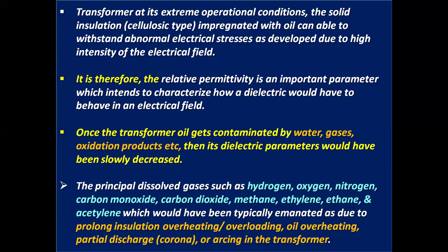It is therefore that relative permittivity is an important parameter which characterizes how a dielectric behaves in an electric field. Once the transformer oil gets contaminated by water, gases, oxidation products, etc., its dielectric parameters slowly decrease.